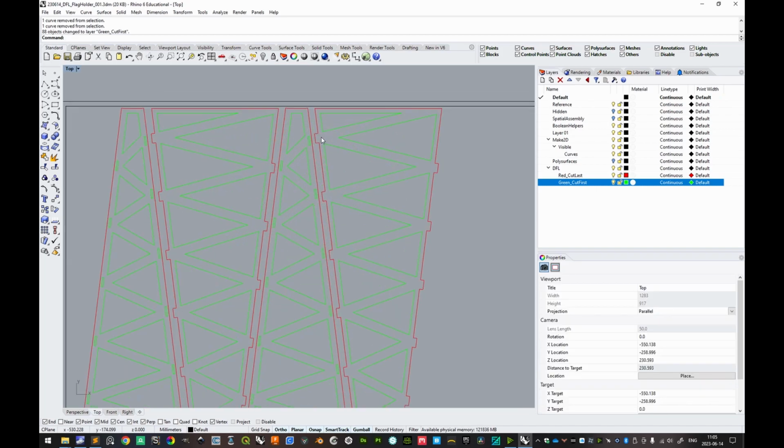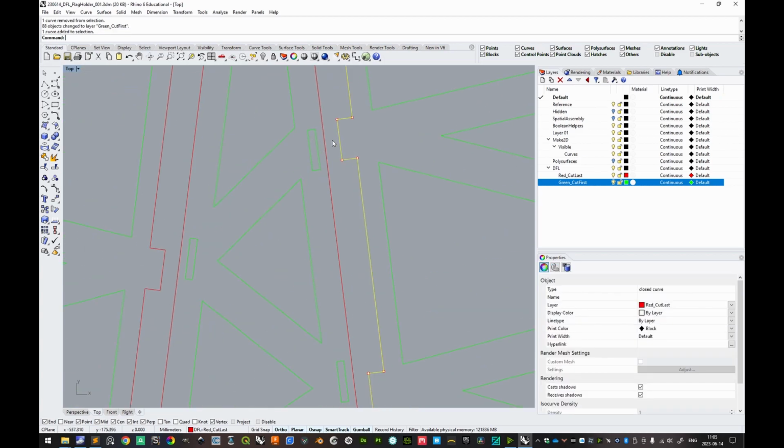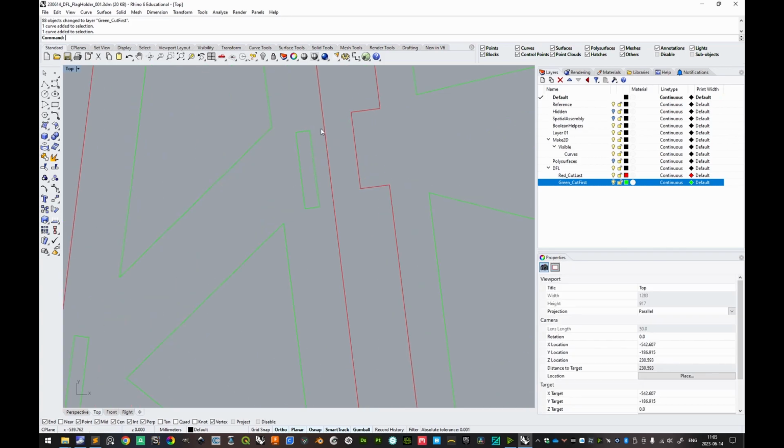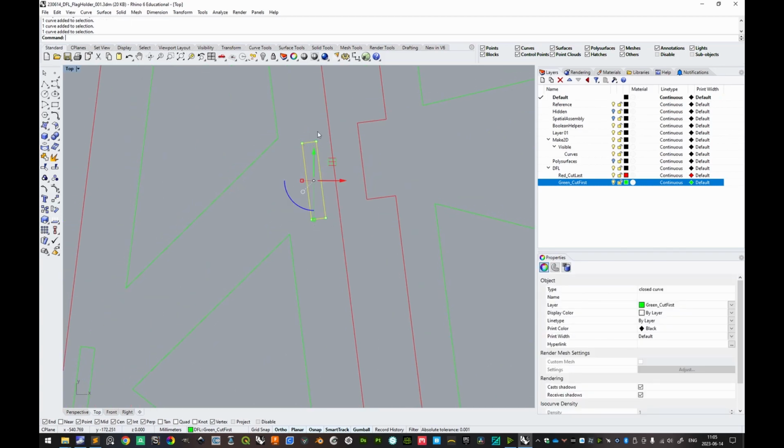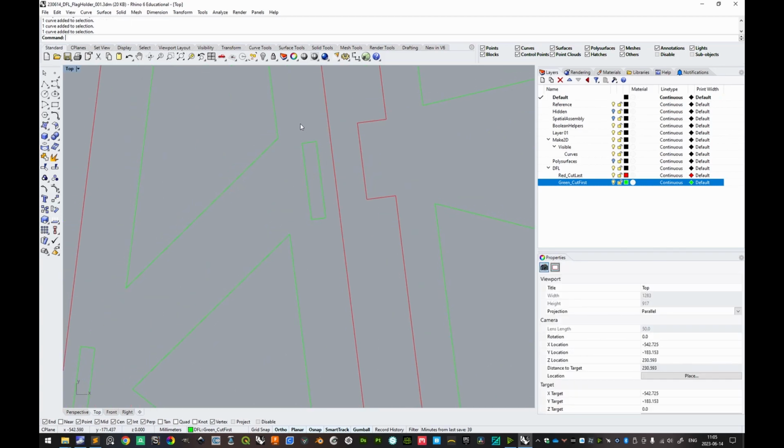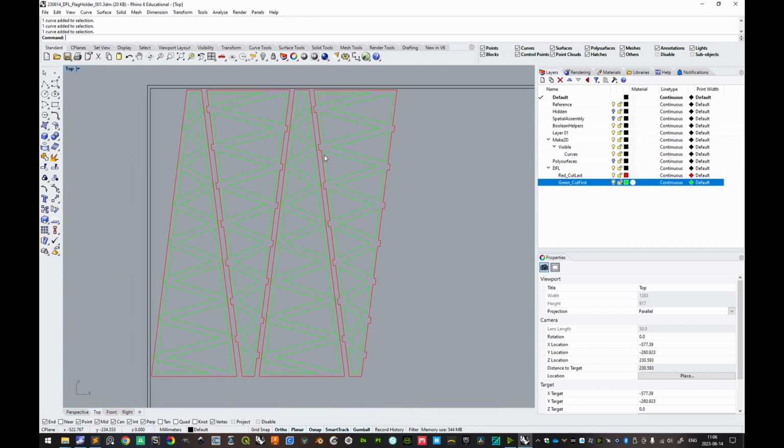We can also make sure that these sort of outsets will be input into these, but we can make these a little wider, because now the hole is exactly the same dimensions as the outsets, and that might be too little tolerance. So we can add like 0.25 millimeter to all of the edges, which means that's like 0.5 millimeters along the axis. So let's see here.